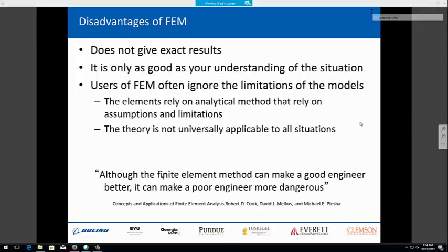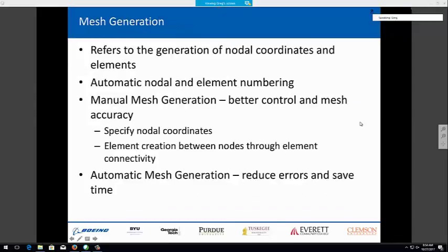And I know this is probably not the material of choice, but I'm going to choose an aluminum alloy. If you see this little plus button right here, when I click that plus button, I'm adding it to a simulation that I would like to run. So I can add aluminum alloy. Again, I'll add some titanium alloy. I'll add structural steel. Okay, so those are the materials that are going to be available for me when I run a simulation. And I'm going to explain some additional things here in a second. So now I've got those materials.